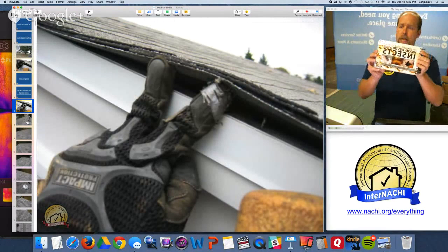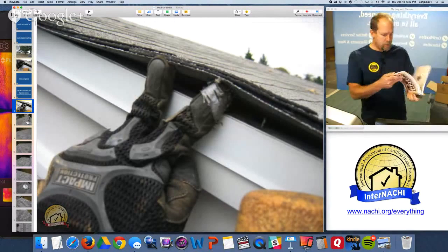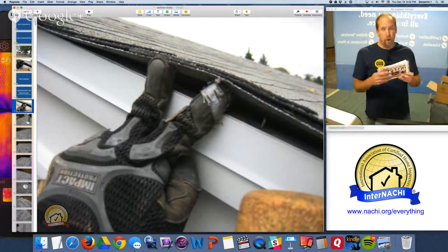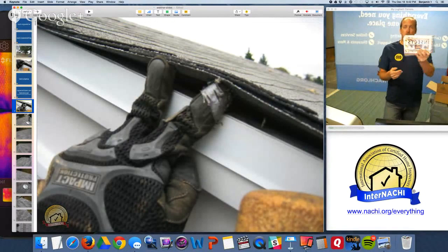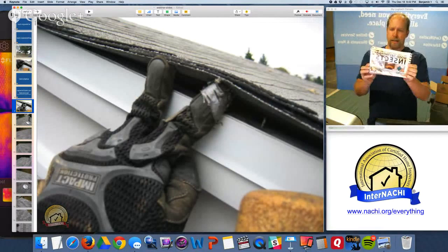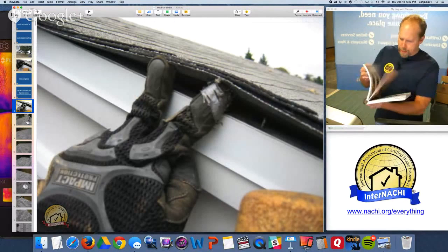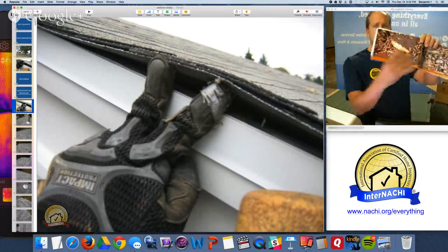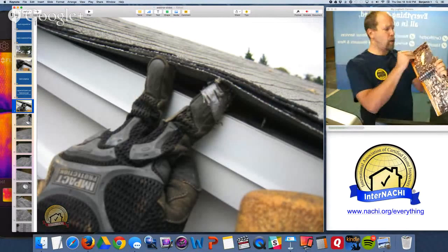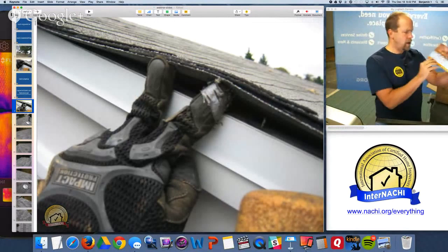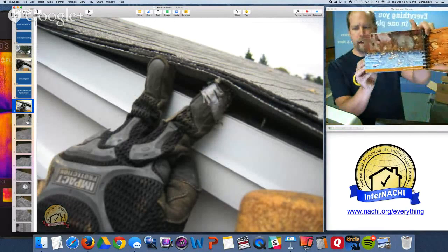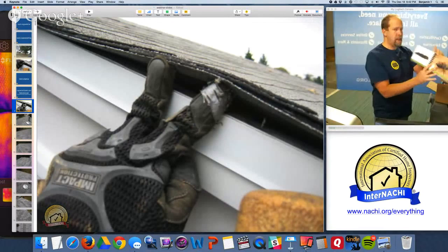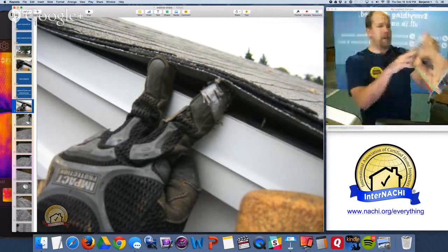You can use one of these. If you're doing a home inspection, you're concerned about anything that destroys wood. Well, moisture destroys wood, moisture and fungus and wood-destroying organisms, insects also destroy wood. And you can use this field guide. It's laminated, and you can use it to help confirm what you are seeing. So you flip through it, and it helps you identify the insect that you're looking at, or the damage that you're looking at, what kind of beetle it is.